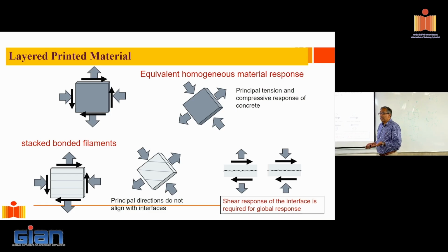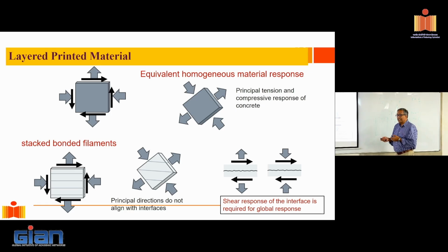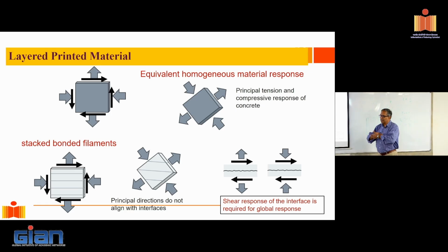So what is going to happen now? No matter whether I like it or not, because the principal directions don't align, the interfaces will be subjected to some kind of shear, either shear with tension or shear with compression. And that would determine the stress response of this fellow.